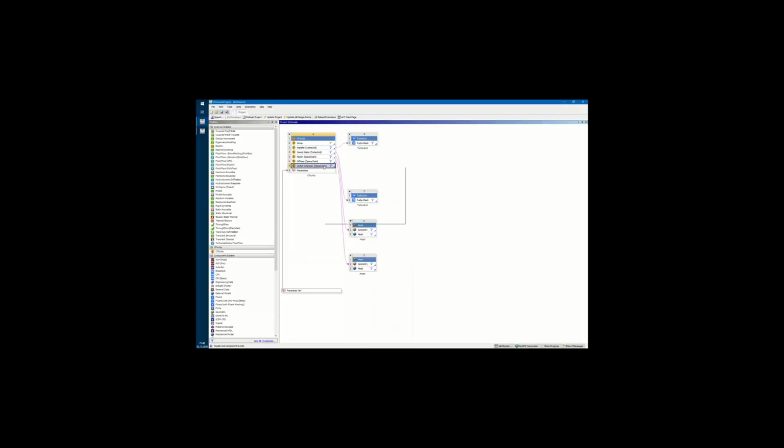And we are going to link SpaceClaim exports to Ansys meshing systems. All components are going to be meshed individually. And after we have set up this workflow, we are going to merge all the outputs from the meshing systems to an empty CFX system.